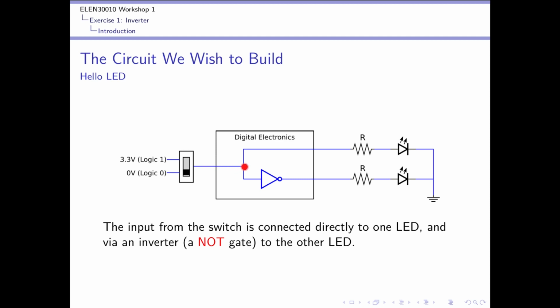The electrons that go down this path here are going to go through this LED here, which means that if 3.3 volts comes in here, then it's going to light up this LED. If, however, we've got 0 volts coming in, then this LED is going to be off because the potential difference across it will be 0. That's the simplest possible digital circuit, and it's not really processing the signal, it's just transmitting the signal, if you will, transferring it from one point to another point.